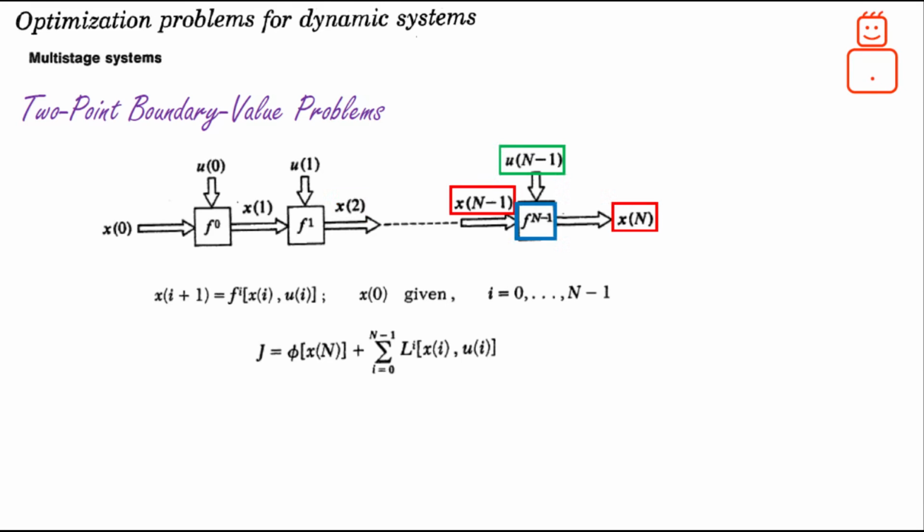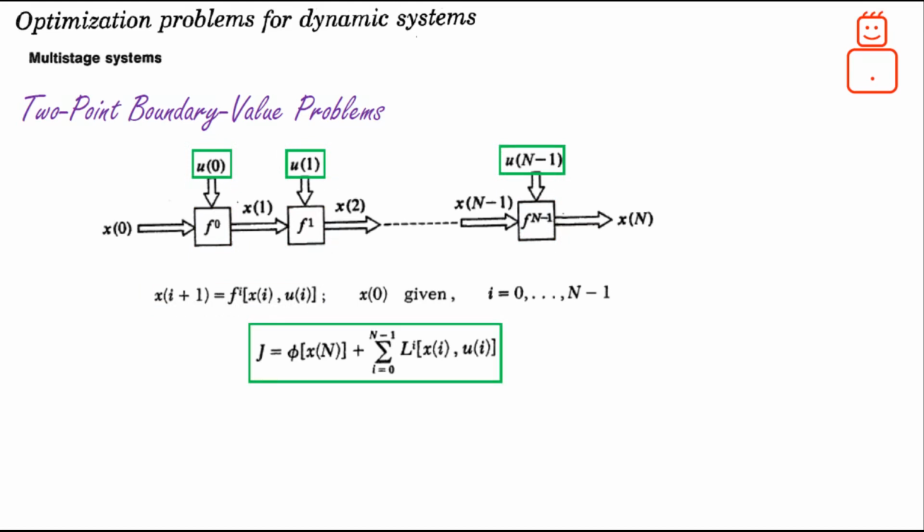I hope at this stage you have realized that we are dealing with a process dynamic that is time variant. As we went through the procedure of predicting a future state of the process, we were assuming different values of the process dynamic at each time index of i. And, of course, we do not forget that the control sequences u of 0 to u of n are computed by minimizing the performance index function J.